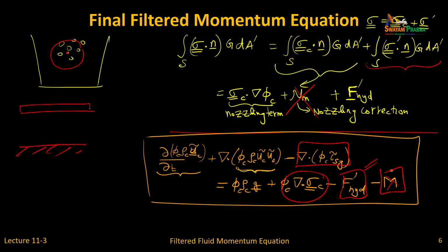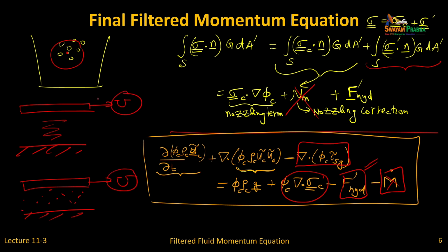Okay. If you take a rheometer and you do an experiment only with fluid, and then with particles, to push it, pull it at velocity u, you have to apply more force with particles. What would you say? Viscosity has increased, effective viscosity has increased.